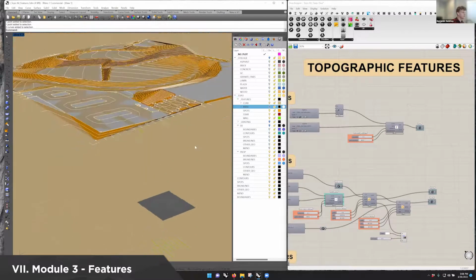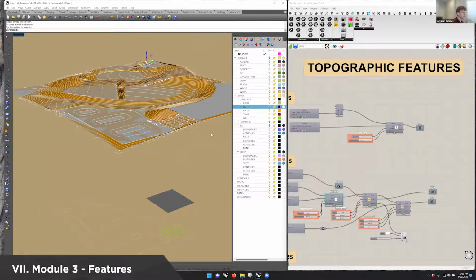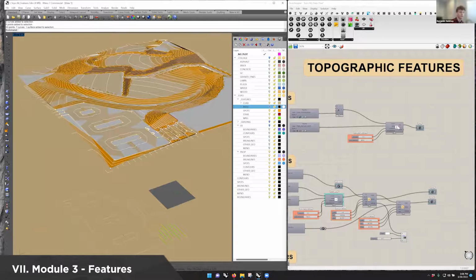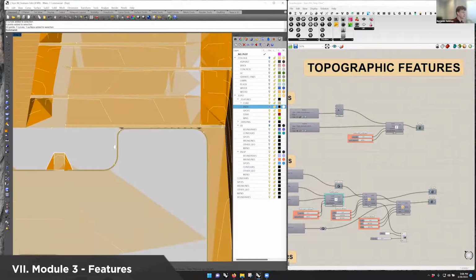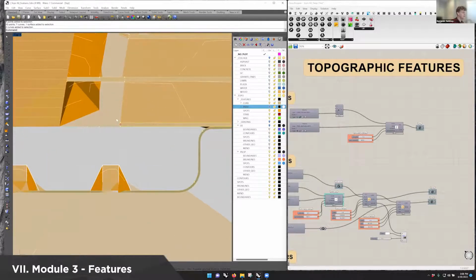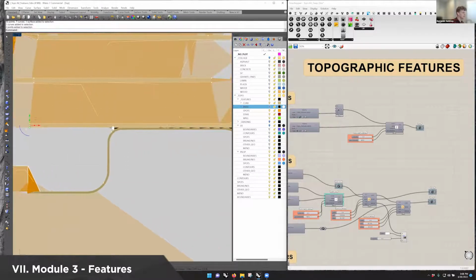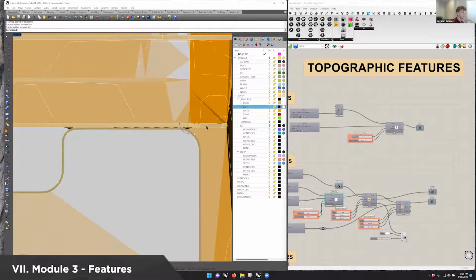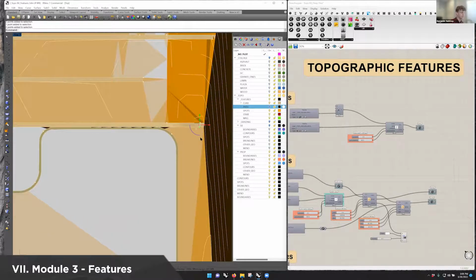But the interesting part is, once you learn a little bit about how these tolerances work, we are constructing all of these walls, this wall over here that you see, and all of these walls right here, simultaneously using one create walls component. So all 16 curves are being processed together with all 114 spots. And it's sorting out which points go with which curves based on how they relate to those curves in plan view. So you can see we have these two lines here, and the spots that relate to them are in plan view directly above them in 2D space or in 3D space.